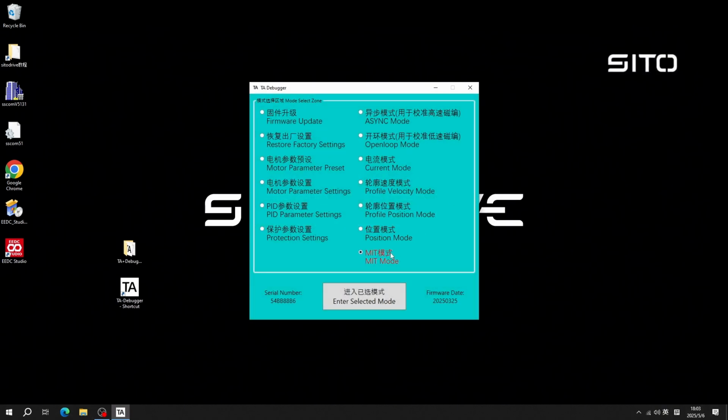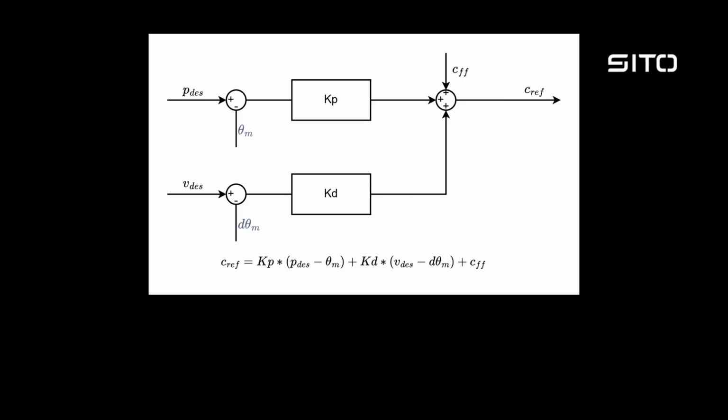MIT mode is a control method that can achieve mixed control of current, velocity, and position. The MIT mode has 5 parameters, among which pdes and vdes are the input values of the position loop and the velocity loop respectively. Kp and Kd parameters are used to adjust the stiffness and damping of the motion, and the output value of the position loop. The output value of the velocity loop and the feed-forward current Iff are added to obtain the reference current iref.